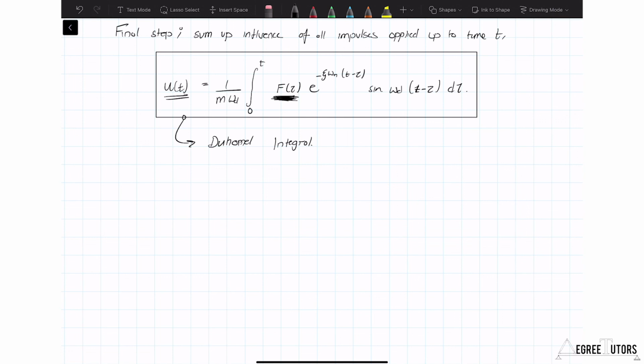Now, although the Millennium Bridge, and there've been many other cases of this human structure interaction and positive feedback, is quite a juicy problem from an engineering point of view, it's also quite rare, and in the vast majority of cases it's going to be absolutely fine to assume no interaction between your pedestrians and whatever structure they're walking on. We'll talk a little bit more about that when we get on to talking about how to model the ground reaction force, the force due to walking on a structure. But just know for now, and in particular when we're dealing with vertical vibration, you're generally not going to have any real strong interaction between the vibration of the structure and the people walking on it. And so the Duhamel integral in this case is a suitable way to go.